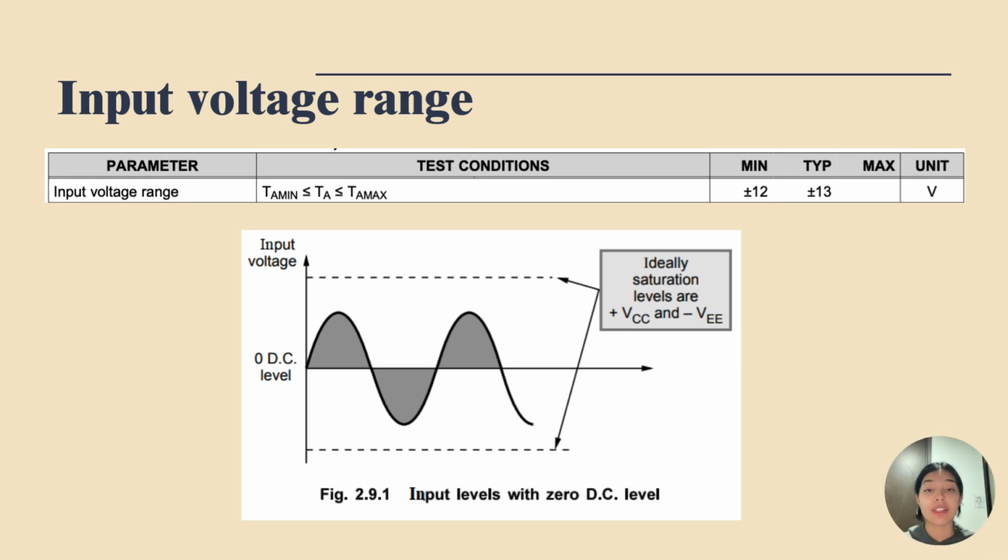Now, according to the test conditions of the LM741, we have an input voltage range with values of a minimum of plus minus 12 volts and a typical of plus minus 13 volts.